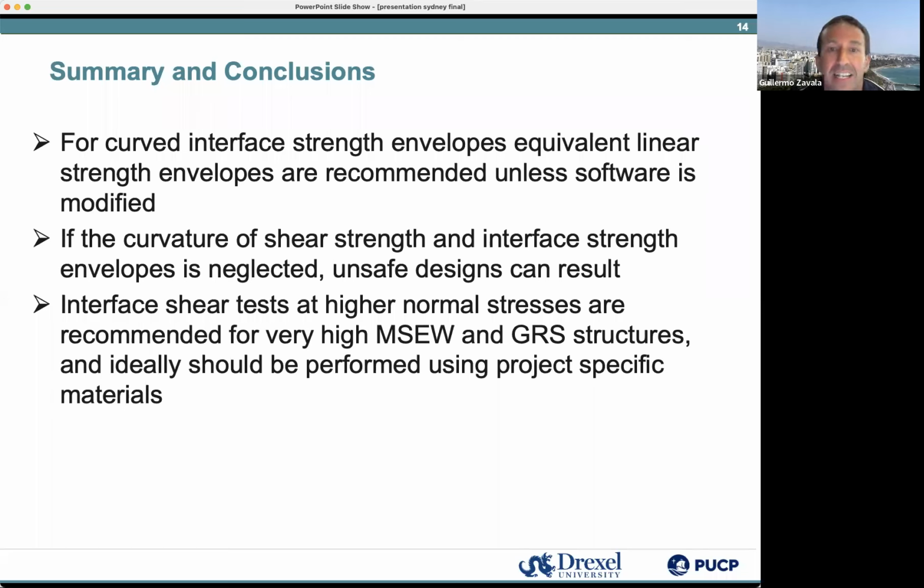And then if you have large projects, you should do interface shear tests at those higher normal stresses. Those are highly recommended, and ideally you should do those with project-specific materials, not with other generic materials.